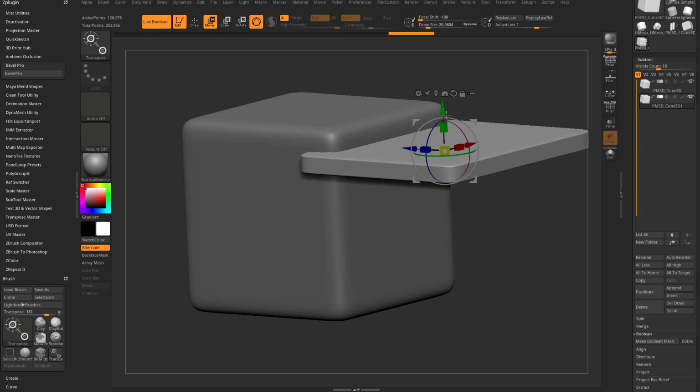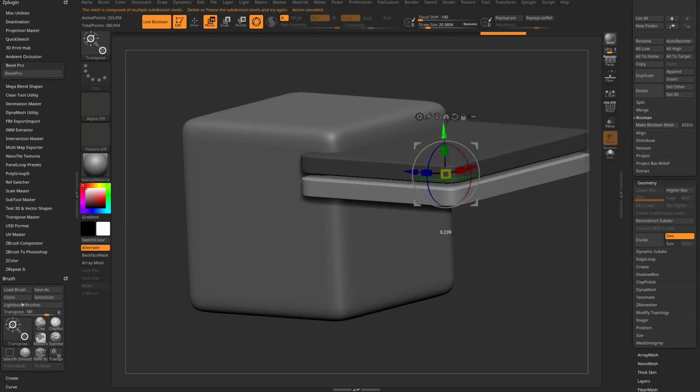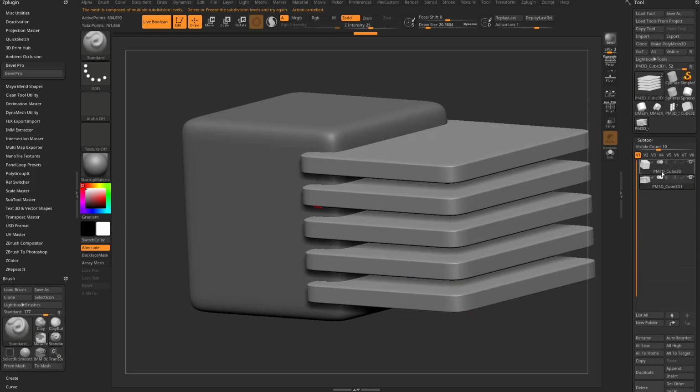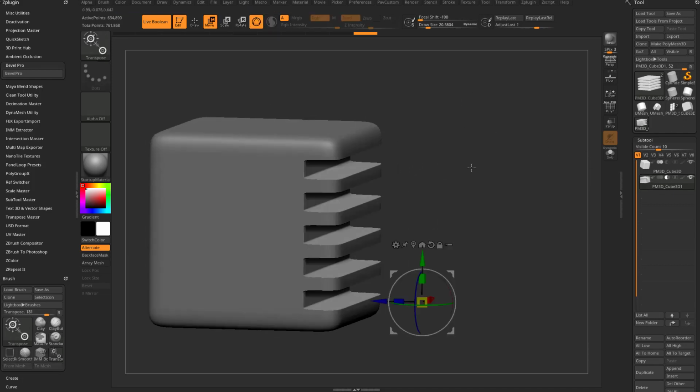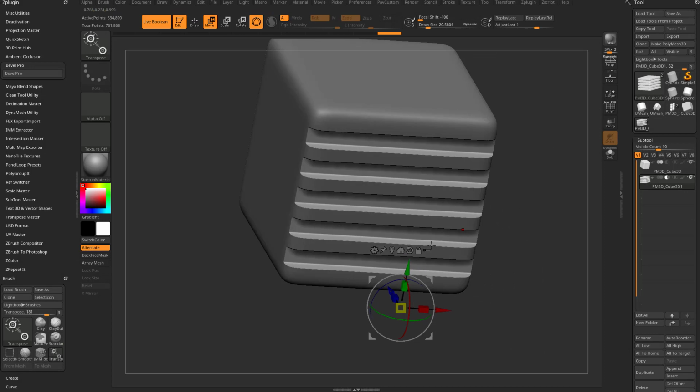I'm going to drag this up, hold down Control and drag this down. Oops. Let's go down here to Geometry, delete lower, Control drag this down, and then we'll just keep repeating this. Control drag to unmask. Go over here, set this to subtractive. Now we have a live Boolean being punched into our mesh here. And in fact, I had to change my mind. Let's go ahead and scale this in.